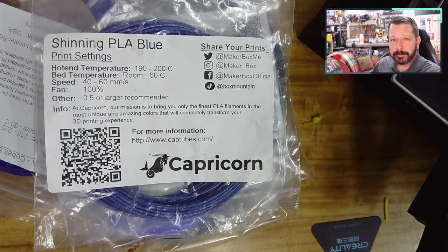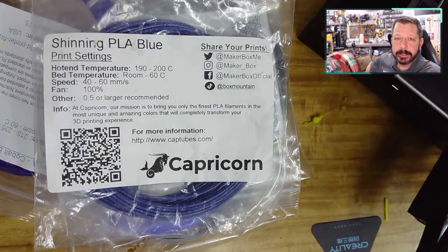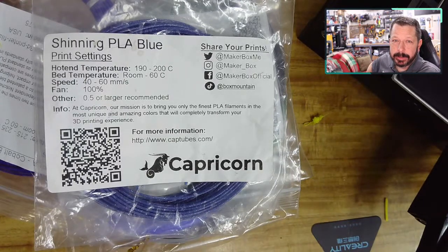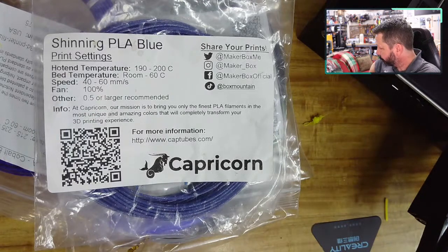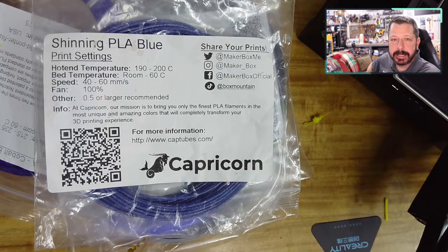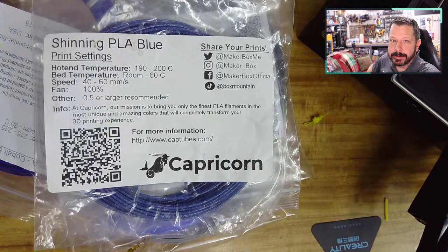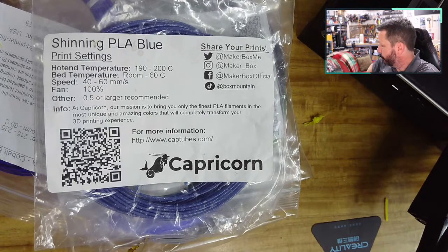I do plan maybe even next week to put on a larger nozzle because I like printing with a 0.6 millimeter nozzle in general. I typically don't use FDM printing for super fine detail, although I will show you some that I've printed that is really good for an FDM printer, but typically I'm using it more for knocking out some part that I want to make. And we need to start making parts for our Rook 2020 printer build, and I want to make those faster, so I'm going to use a bigger nozzle.